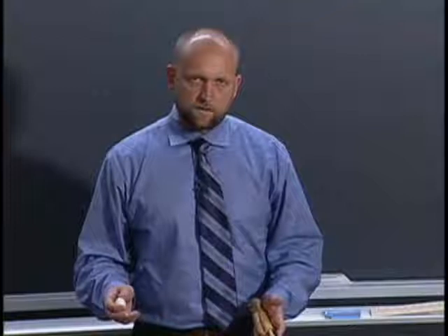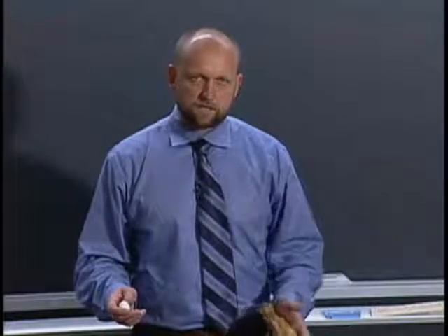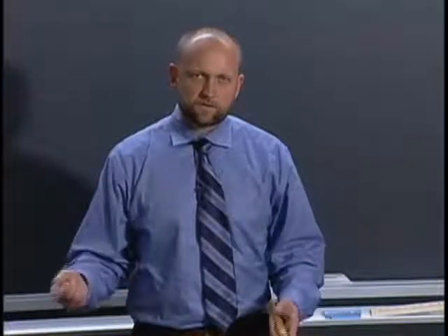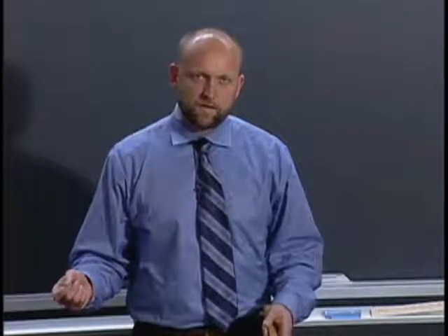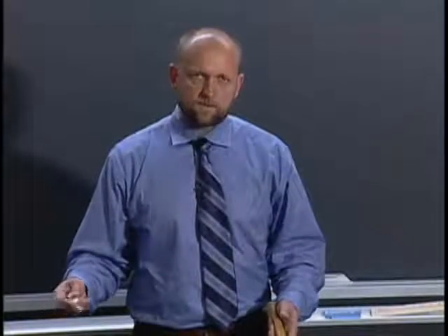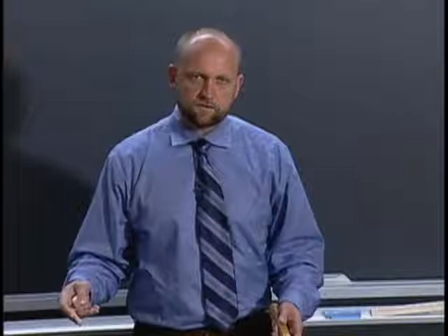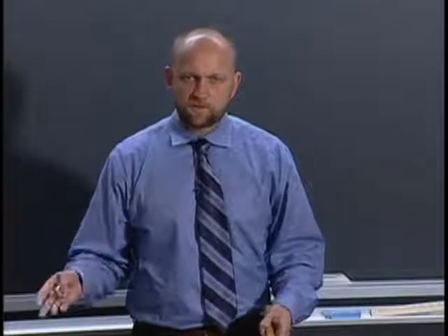In the third pause of the Blossoms video module on design of mechanisms, I pose a question to the students. They have 3 points that characterize the motion of part of a mechanism, and I ask them how they could determine the point at which they need to locate a joint or a bearing. Now, this is related to the geometry of circles, and I show a construction technique in the video itself after the pause that gives a little bit of detail. At this point, I want to show just a little bit of the geometric theory behind that construction technique I show.